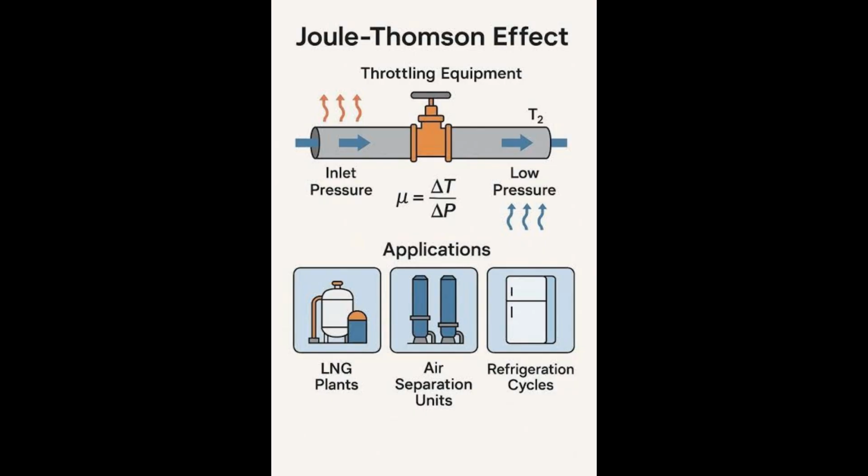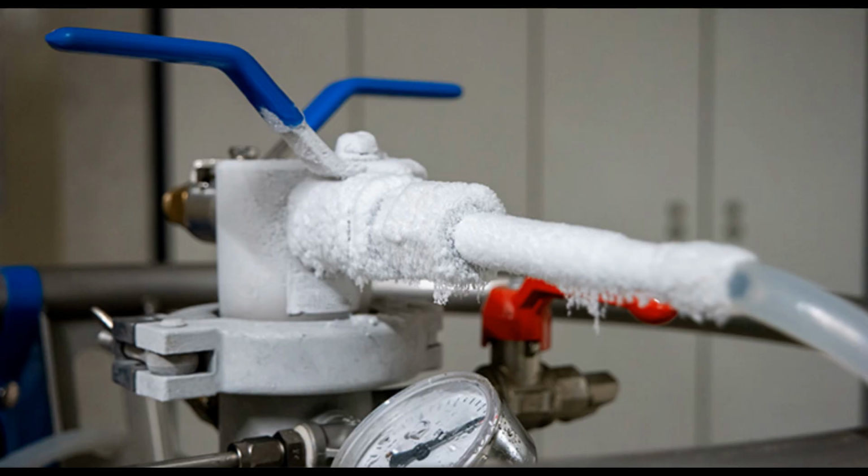Cooling helium from room temperature to 4.2 Kelvin requires cryogenic refrigeration, relying on techniques such as Joule-Thomson expansion or gas compression. The key energy values are that cooling energy demand is several thousand kilojoules per kilogram just to get the gas cold, and then the latent heat of liquefaction is much lower, only 20.4 kilojoules per kilogram. Far lower than the latent heat of liquefaction of nitrogen, which is 199 kilojoules per kilogram. This means that helium requires extensive refrigeration, but relatively little energy for the actual phase change.